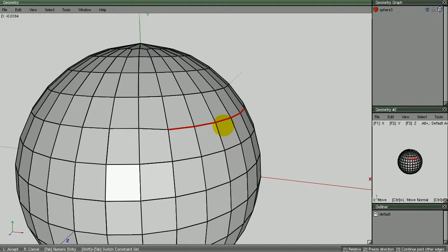In this case, we have absolute selected. When you have the absolute selected, it is actually measuring in terms of Wings units of measurement, how far the slide is occurring, both in the positive and negative direction from 0. So from 0 it'll go up to positive 0.19 and down to negative 0.19. And so this allows you, through numerical entry, you can hit tab and actually enter the numbers directly on your keyboard, or you can use the distance constraints you have set in your preferences by holding shift or holding control or holding alt. You can then move based on the distances in your constraints.